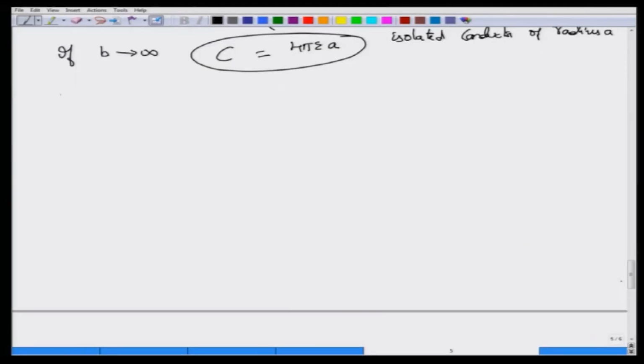Now, let us try to apply the V method here. We will discuss rigorous solutions of Poisson's and Laplace's equations later. What we are going to discuss is what is required for finding the capacitances in these simplified structures. For the V method, I need to solve del square V equal to 0. Of course, I need to solve this in the spherical coordinate system, and since V is a function of r only, we can use only the terms corresponding to V of r.